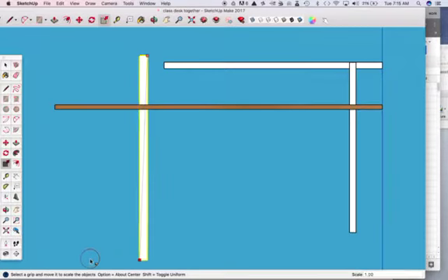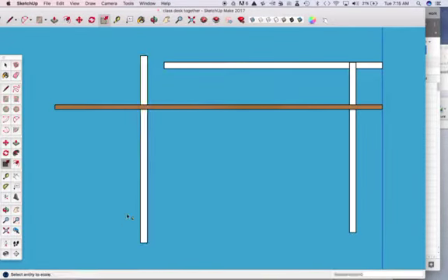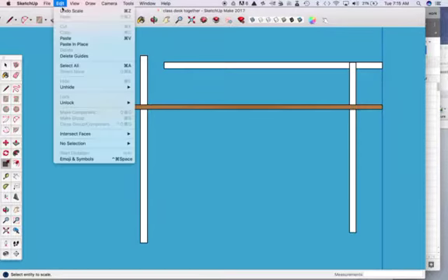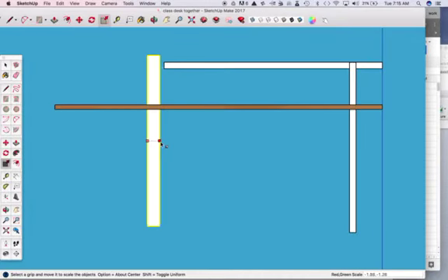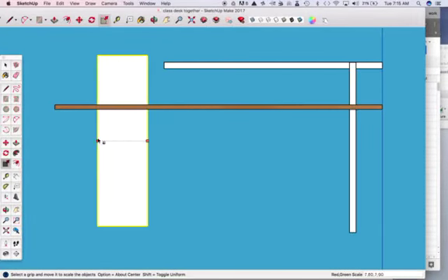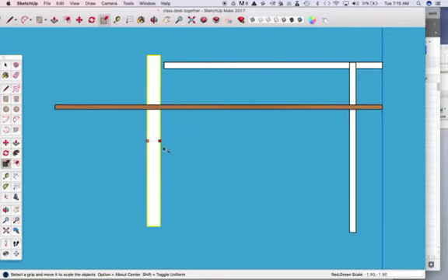So I could make this thing bigger this way, which I'm not going to do. So I need to undo that. Or I can make it scaled negatively in a direction I choose. So that's what I am going to do. So remember, once I click the button, I can move any way I want. But I want this to be locked to, no, actually, if you click the middle one, you can only go this way, so that's good. But if you look in the lower right corner at the numbers as I do this, how they're changing, I want to flip this thing around. So I need it to be a -1 for both the upward and down and left and right direction.